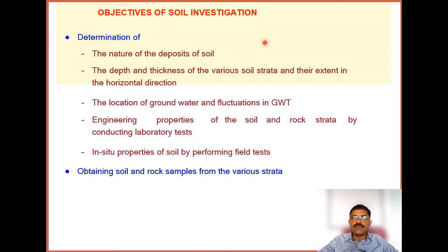Soil profile, you might have heard about soil profile or bore log. It all comes under this, where you go for investigation on the different soil layers in the ground. Soil, not only soil, rock and other geological materials. So the third one is related to the groundwater table, and the fourth one is related to the engineering properties.